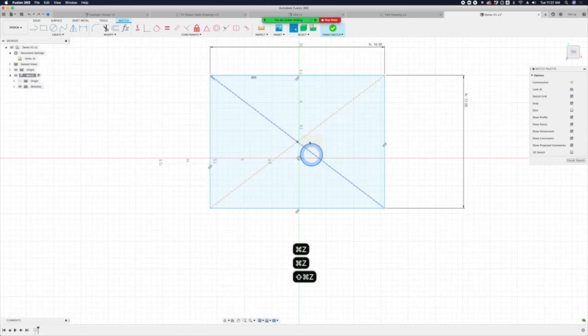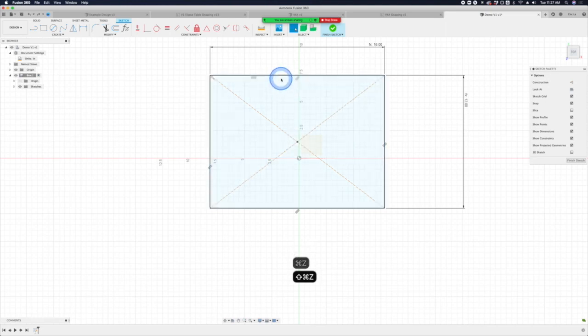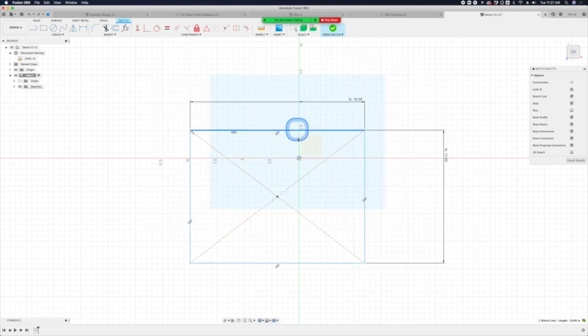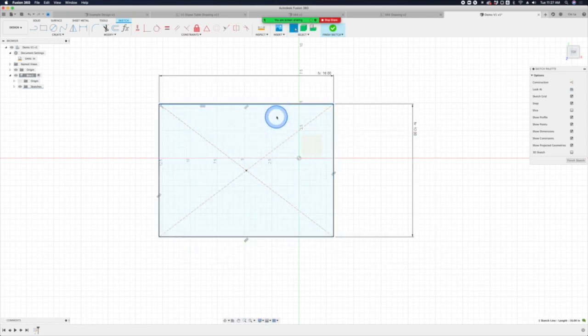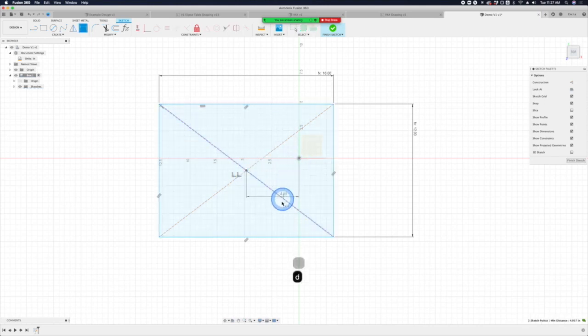It's basically because this box, we know how wide it is and how long it is, but this point is absolute. This is 0. Once I tell the sketch where this point is in relationship to this point, and you have to be aware of how you're dragging so you're not defining a hypotenuse or something there.